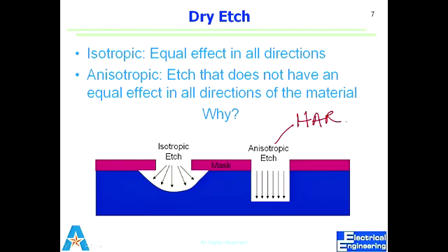But then, in a simple dry etch process, it's called RIE, reactive ion etching, they cannot go too deep, because once they get into something which is high aspect, they tend to collide with the walls. And the product cannot be removed too fast before new etchant comes in and etches further. So there's a limitation on how deep we can etch using RIE, reactive ion etching.